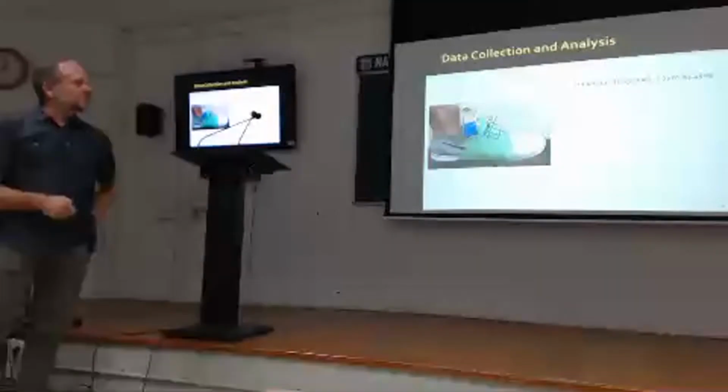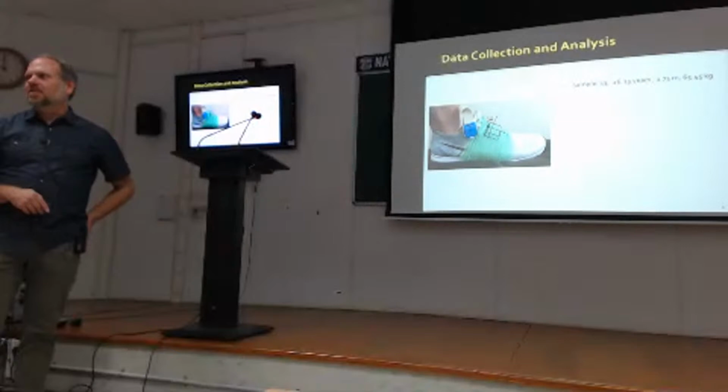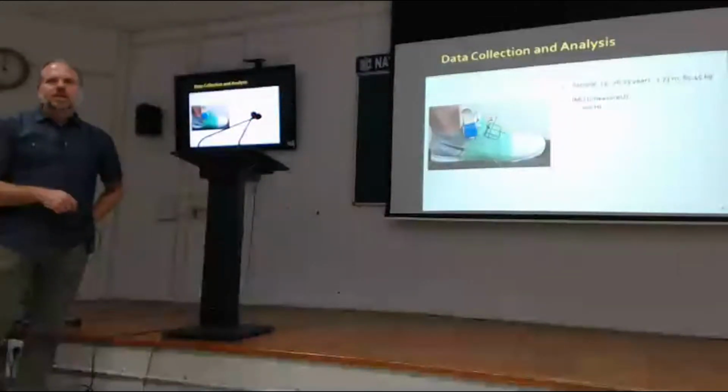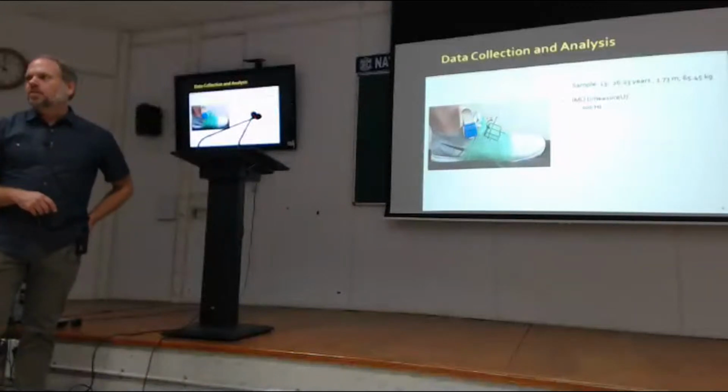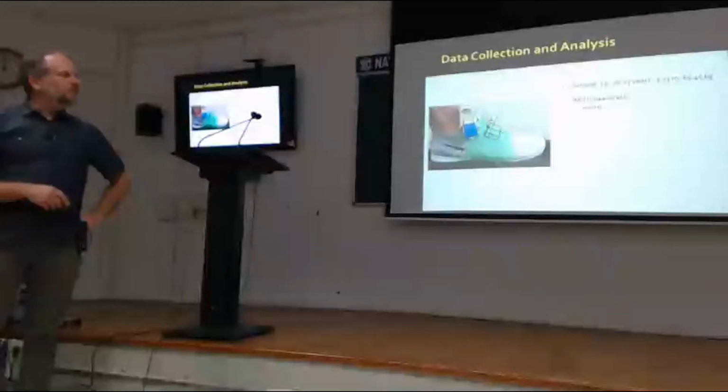The instrumented subject is an average graduate student, essentially. So all of our grad student friends came to the lab to get tested. Not a very representative sample, especially of amputees. But this measuring system is an IMU from New Zealand that has the 9-axis system. So it has 3 accelerometers, 3 rate gyros, and 3 magnetometers.